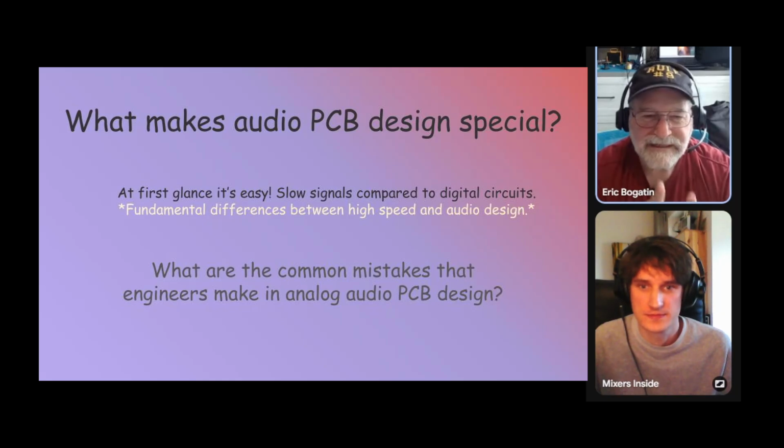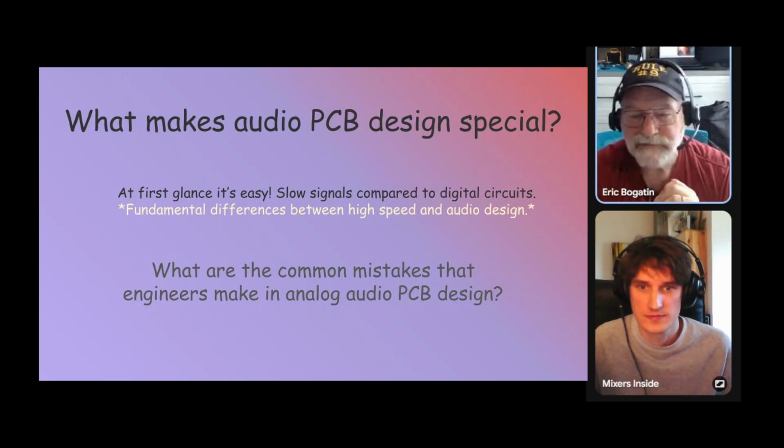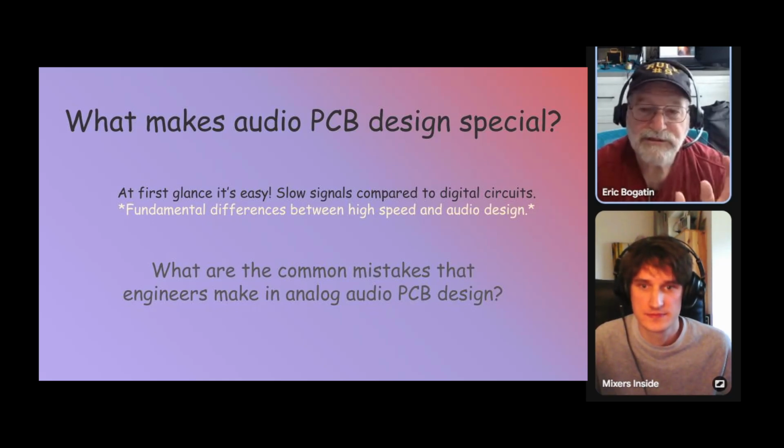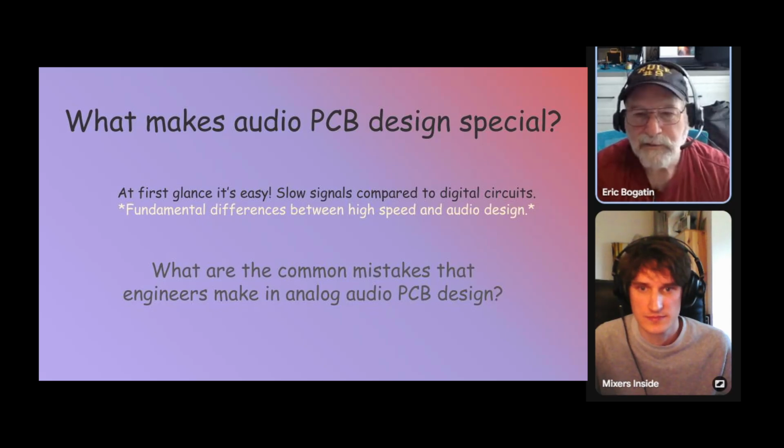That 10%, a tenth of a percent crosstalk now can completely degrade your signal. And so you've got to watch out for the crosstalk from the digital signals that are around, and they're going to create noise on the power rails. They're going to create noise as crosstalk between signals. They're going to create noise because of their return currents in the planes as well. And so you've got to be careful about isolating digital components from the analog components.